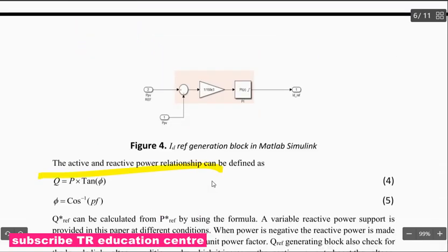Next, the active and reactive power relationship can be defined as Q equals P tan phi, where phi is cos inverse of the power factor. The Q reference can be calculated from the P reference by using this formula. The variable reactive power support is provided in this paper at different conditions.